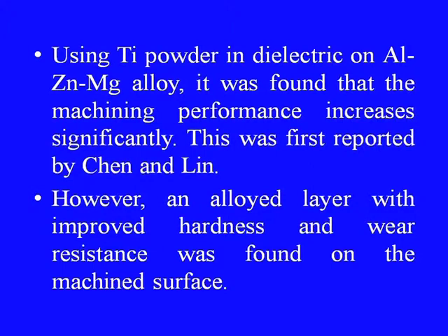Using titanium powder in dielectric on aluminum, zinc, magnesium alloy, it was found that the machining performance increases significantly. This was first reported by Chen and Lin. However, an alloyed layer with improved hardness and wear resistance was found on the machined surface.